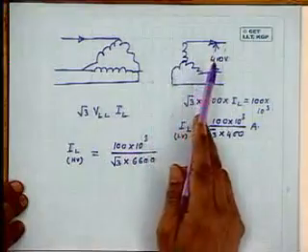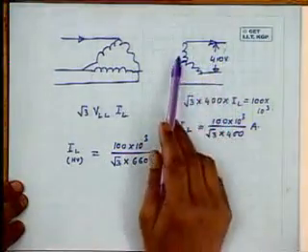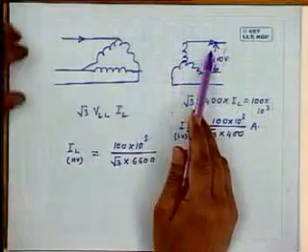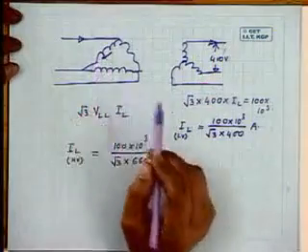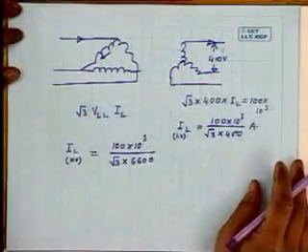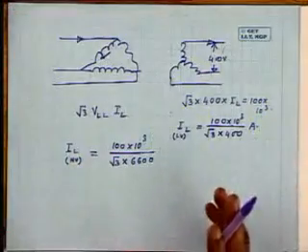Winding currents will be how much? It may be equal to the line current or may not be. For example, for the LV side, winding current is same as that of the phase current, and here the winding current will be now root 3 times less. Those things you should keep in mind whenever you work with a single unit of three-phase transformer. Why is it highlighted?